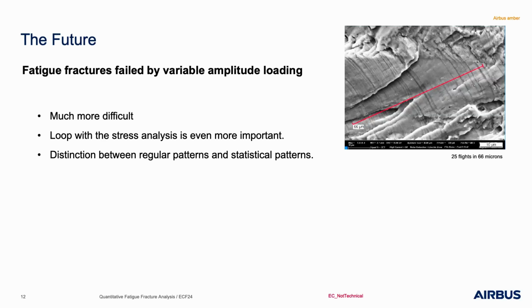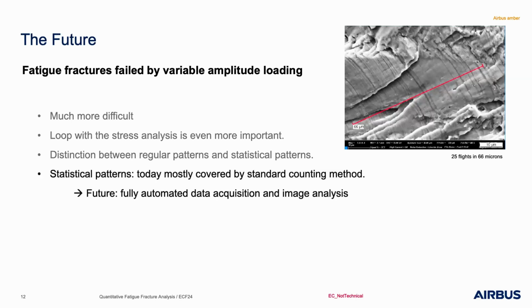Statistical patterns as they typically arise in failure analysis from in-service parts, but also regular patterns as we also have very often, because we have also often test parts from our full-scale testing or from the testing departments, just to see there the growth of the fatigue cracks. In case of statistical patterns, today it's mostly covered by the standard counting method.